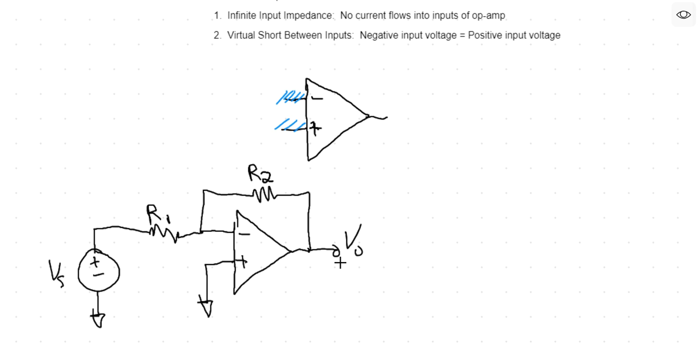So these are extremely useful, and they have a lot of real world applications. Anytime you have a small voltage signal, in order for that to be useful, a lot of times you need to amplify it before you send it to an analog to digital converter, for example.